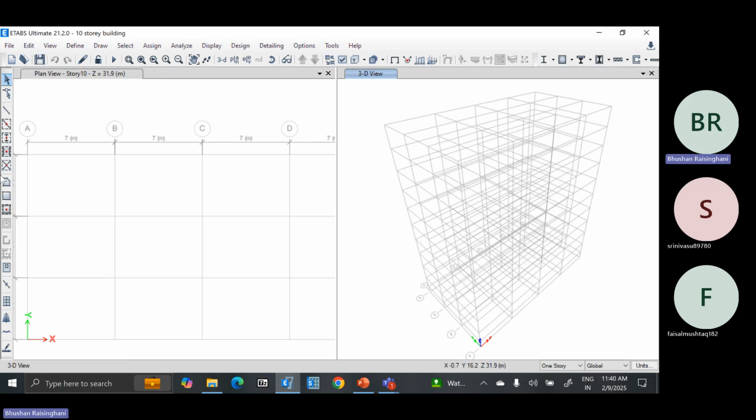Now these are the draw tools and selection tools. This is for the beam. Point to point modeling. This is for the beam, that is the object, full object modeling in one click. Column modeling. Then this is quick draw secondary beams. Cross bracing. This is for the slab point to point. This is for the slab, if the geometry is not rectangular, you can use these options. If it is rectangular, you can directly click between the grids and create it.